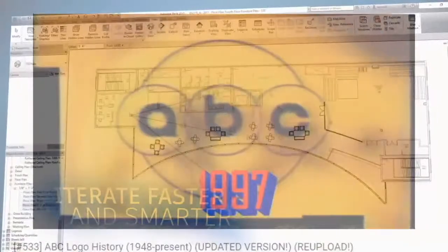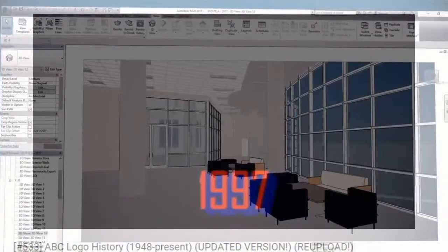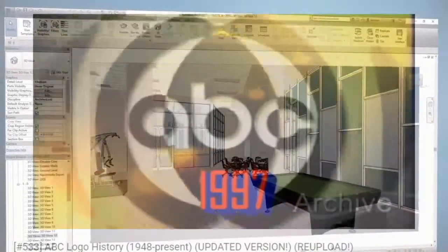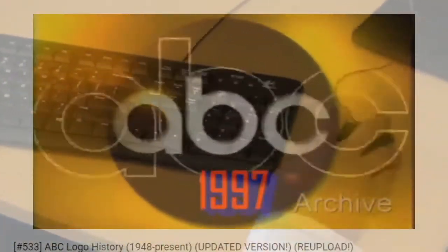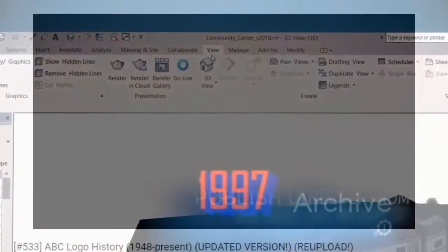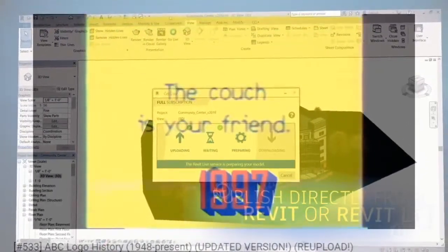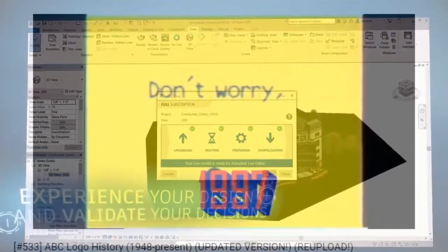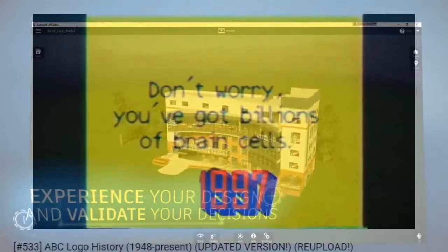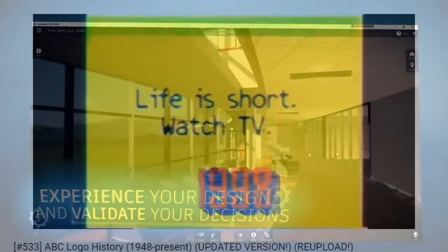So, okay, click the architectural tab in the ribbon and select floor slab edge from the build panel. This tool is also available from the structural tab. If necessary, orbit the 3D view so you can see the bottom of the lowest floor slab. Pick all four bottom edges of the floor slab at the level named ground. Activate the section view. Okay, well, first of all, let's get to that view.